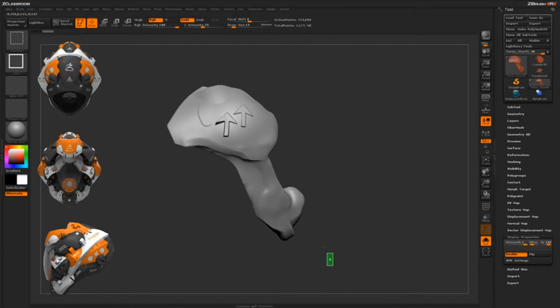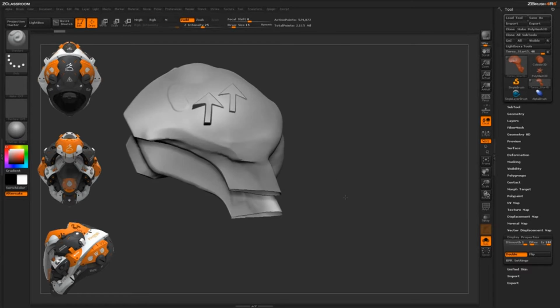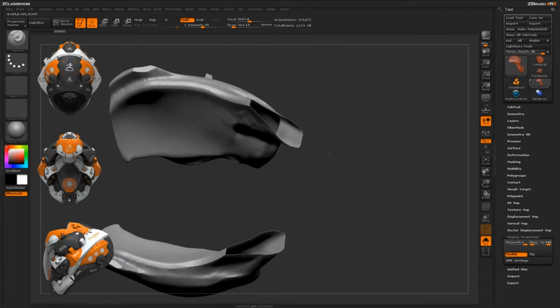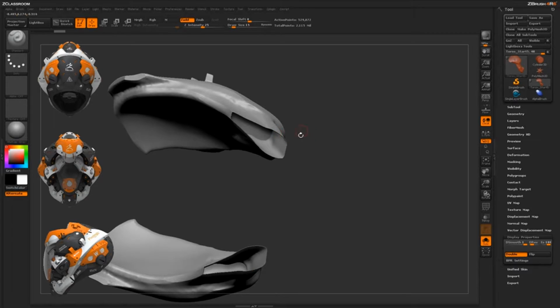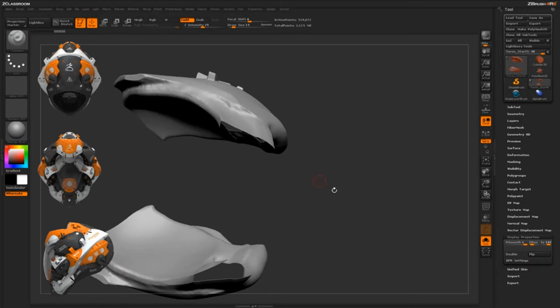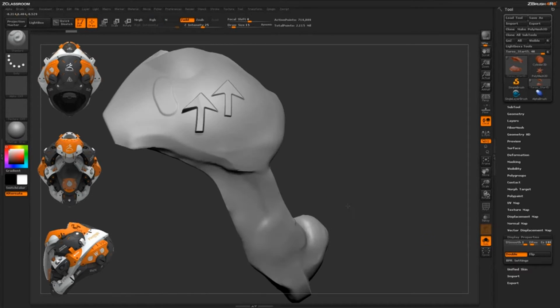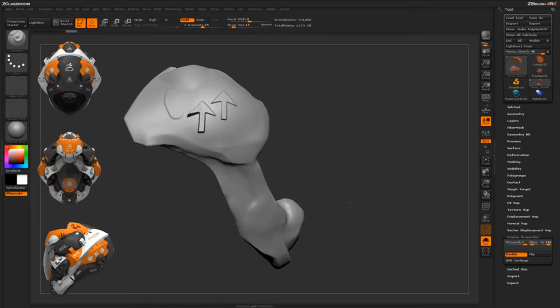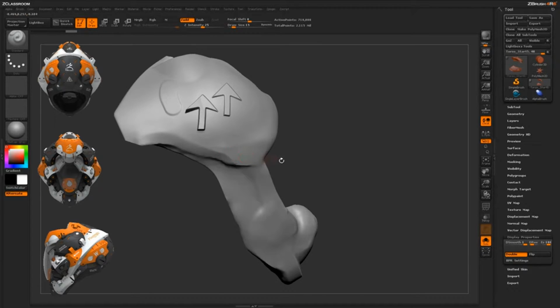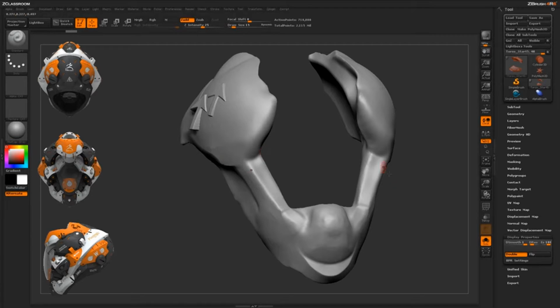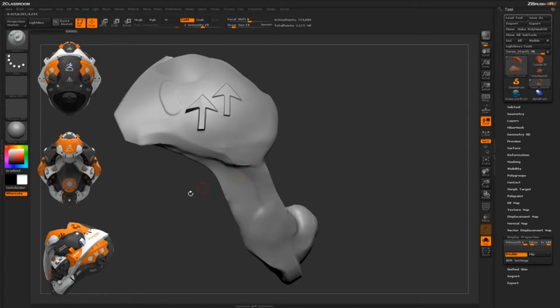This is helpful when you're sculpting on a mesh, and if you hold Control-Shift and hide a part, you can see the interior surface to check for problem areas and things like that. So if I turn double off, you'll see it's no longer rendering double-sided, and if I turn it back on, I'm getting that feature like that. Turning this on is a requirement to get this Projection Master option to work, to project the details on both sides of your model using that symmetry plane.